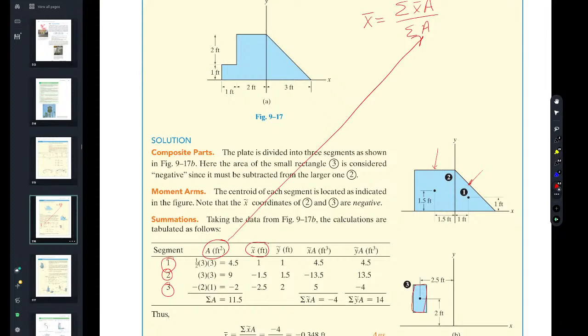Okay, so here we go. He listed his x bars, so he found each one of them, and his y bars. Now you have to make sure you put this exactly where it needs to be, meaning it has to sit exactly in this spot to subtract that hole out. So it's 2.5 over to the left and 2 up to the centroid of that. And the other thing you have to do is respect and use the coordinate systems.